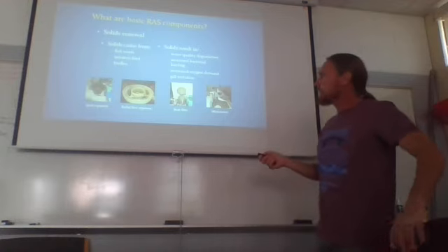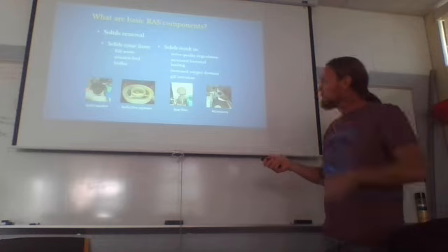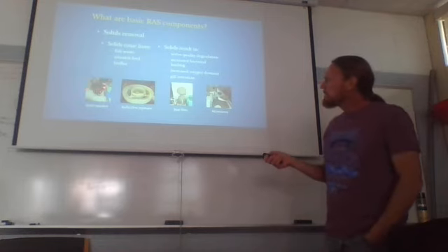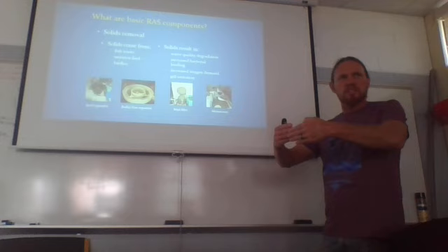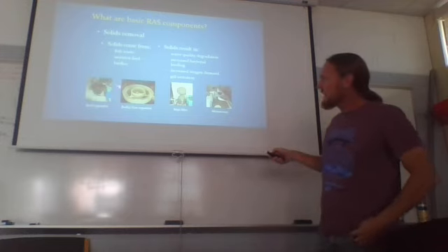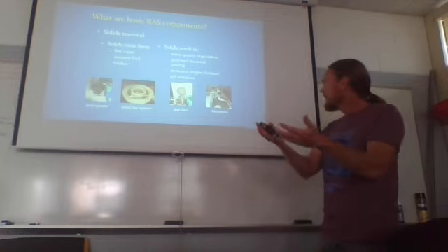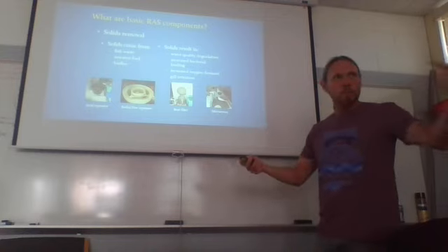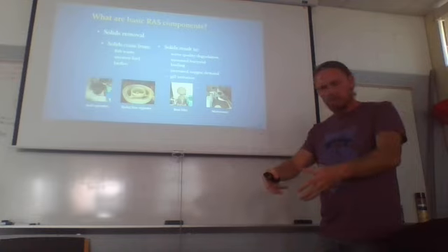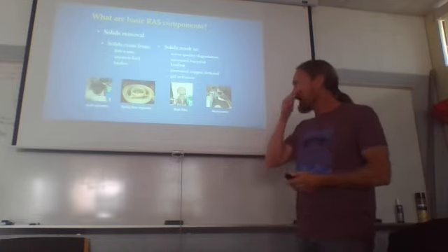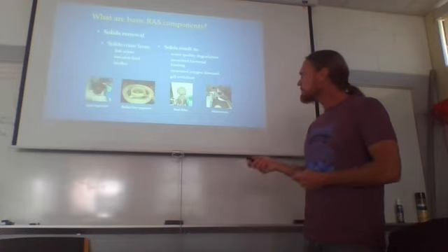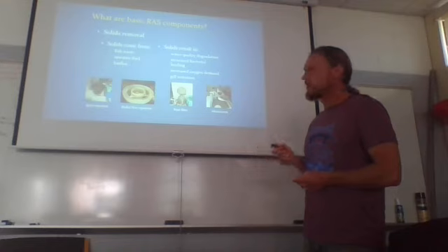Some types of solid removals. A swirl separator is basically, like I described in the tank, creating a swirl, and that's carrying things toward the center. And in some cases, they may have an outflow that sucks that out. I've seen really simple ones that are just basically a settling tank that the water swirls around, and you clean the bottom yourself once every couple of days, and it's just removing water from the system.